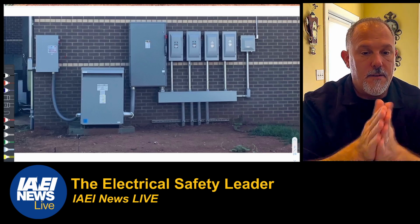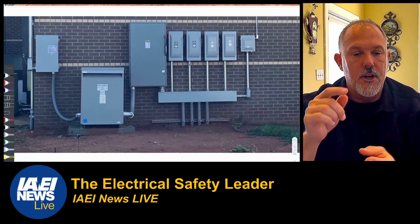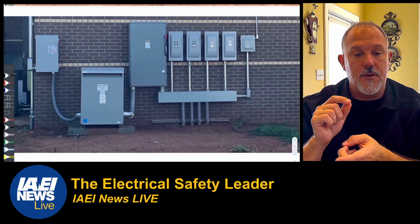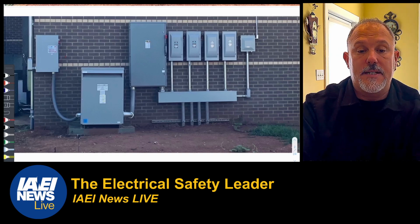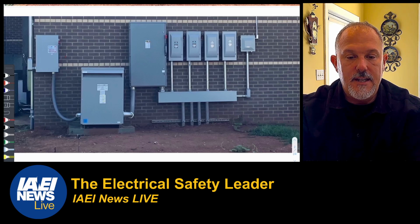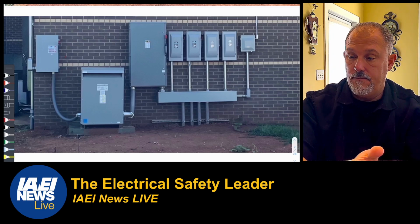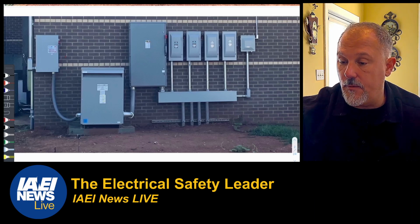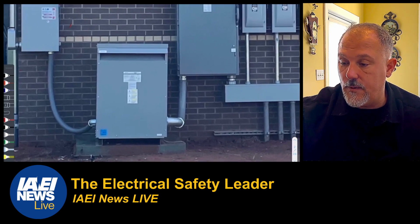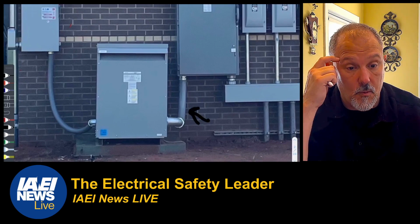Thank you. All right, so we're outside conductors. Where the conductors are located outside of a building or structure, except at the point of load termination, and comply with all of the following conditions. 1, the conductors are protected from physical damage in an approved manner. So what do you guys think? We've got the transformer secondary conductors. They are in a raceway. They're very well protected. I would argue we meet condition number 1.